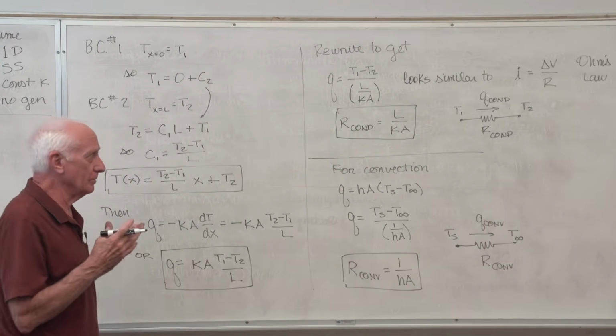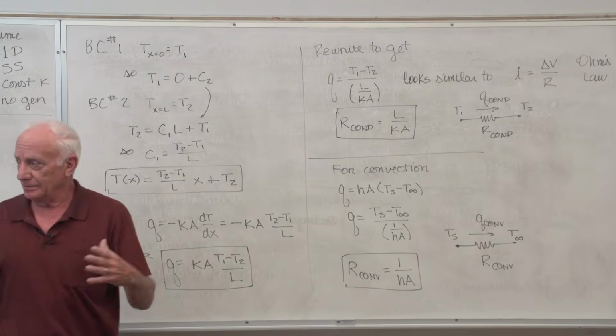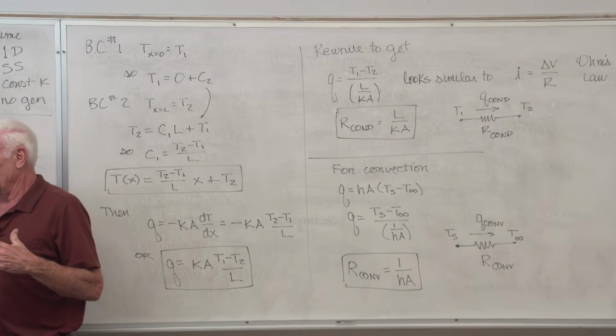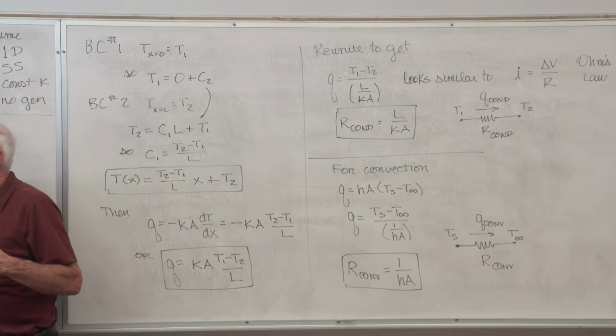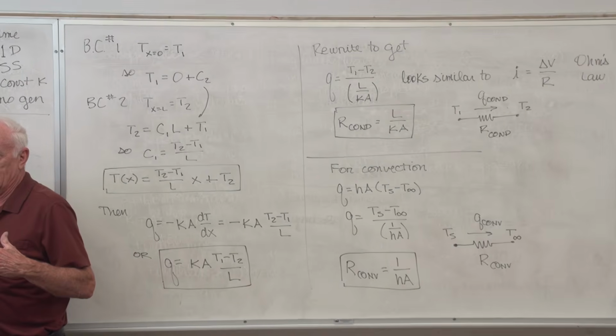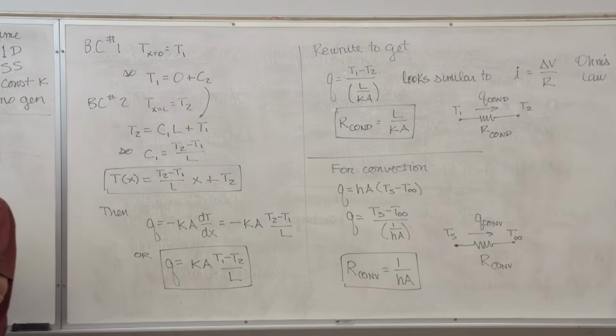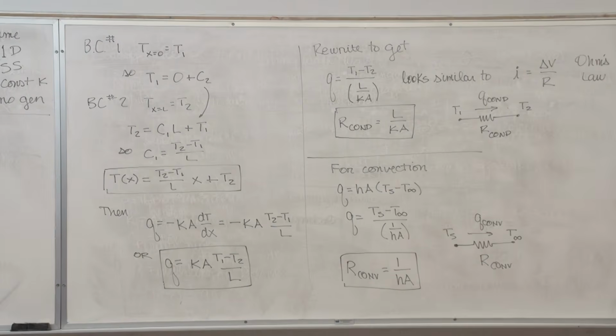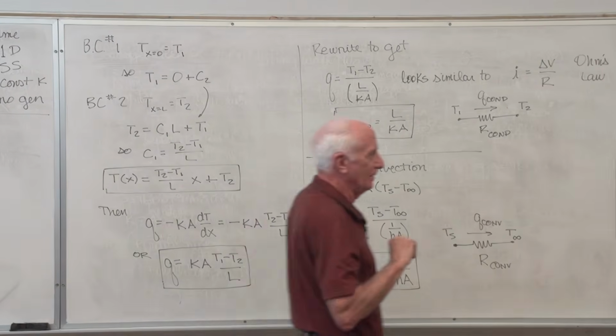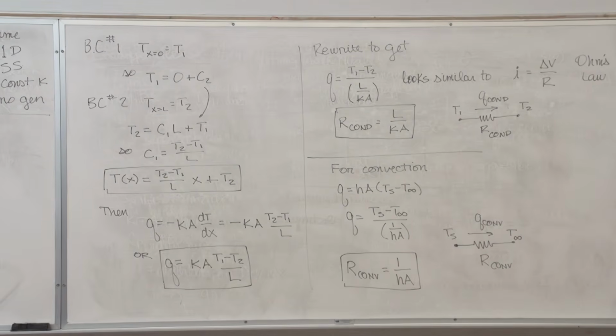So obviously, what we're going to do is combine these guys into plates. This might be a copper wall with insulation on the wall, convection on both sides, 4 resistances, 2 conduction, 2 convection. So we'll be modeling walls like that. You want to model that concrete wall right there for analysis? Not a problem. There's a convection resistance with the air in this room. There's conduction through this solid concrete wall. And there's convection on the outside hall side wall. 3 resistances to analyze that wall thermally.